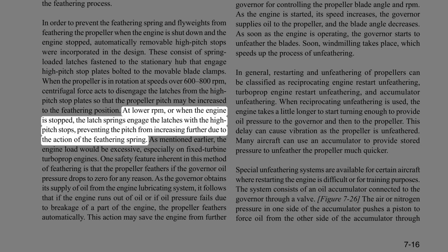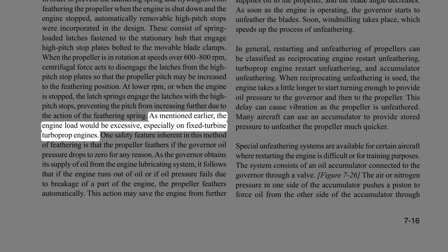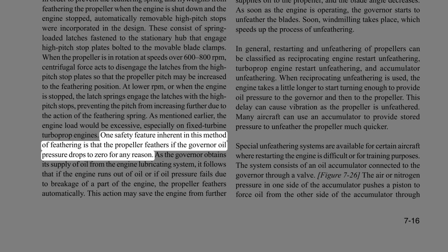At lower RPM, or when the engine is stopped, the latch springs engage the latches with the high-pitch stops, preventing the pitch from increasing further due to the action of the feathering spring. As mentioned earlier, the engine load would be excessive, especially on fixed turbine turboprop engines. One safety feature inherent in this method of feathering is that the propeller feathers if the governor oil pressure drops to zero for any reason.